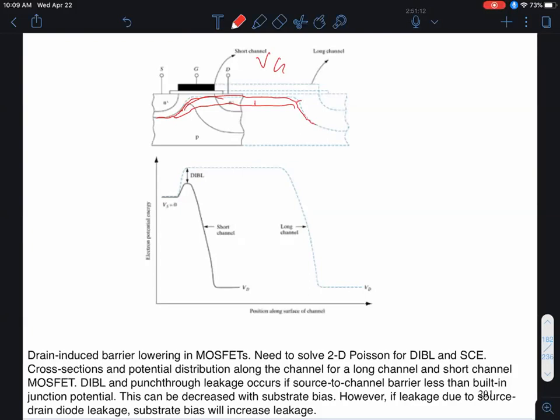Now let's see, I disobey Dr. Dennard and I scale down the channel length from this channel length to this channel length, roughly by what, a factor of maybe 3 in this case, okay? So that's L1, that's L2, so L2 is roughly 1/3. But I don't follow Mr. Dennard's laws. I don't scale down the vertical dimensions, okay? So my junction depths are the same. I haven't changed the channel doping. My depletion region is the same. Everything else is the same. What's going to happen?